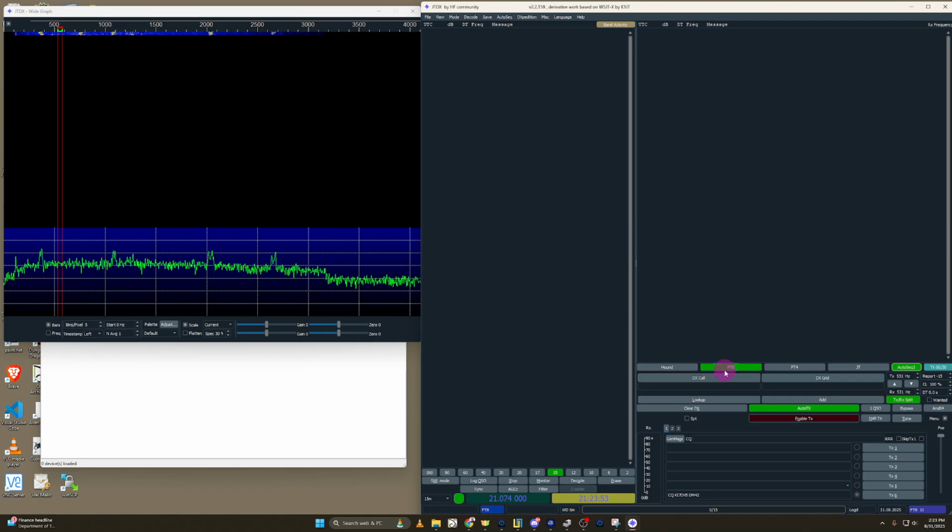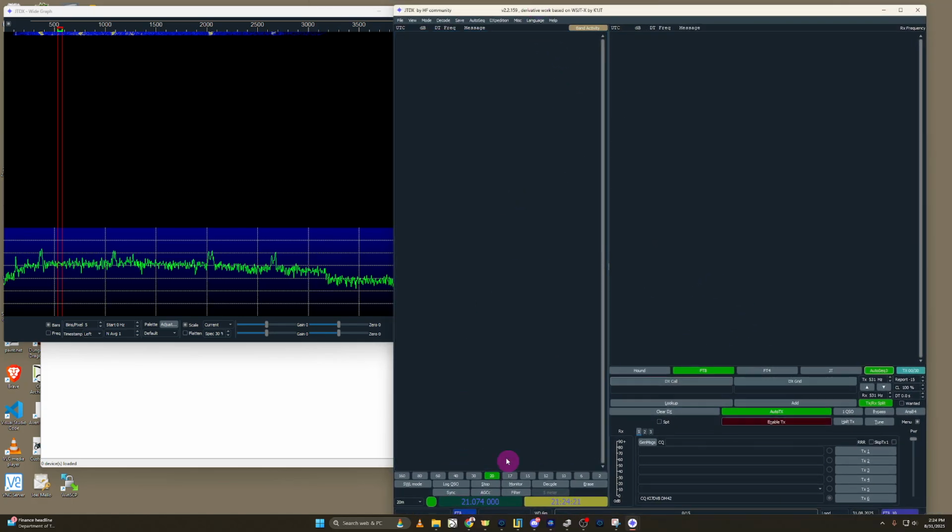Okay, once we have the settings configured, next here inside of JTDX, all we need to do is pick our band. I want to operate on FT8, and I'm on 15 meters right now at the moment. I found with the G90 rig control driver, another problem was that it was not correctly adjusting the frequency, the VFO on the radio. Like for example, if we want to move over to 20 meters, we click on this and then use the drop down here to go to 14074. And that would not update the radio. I don't know if that's just a bug with JTDX, but sometimes this just doesn't work properly. I haven't figured out that part of it just yet. So now let's just operate on 15.